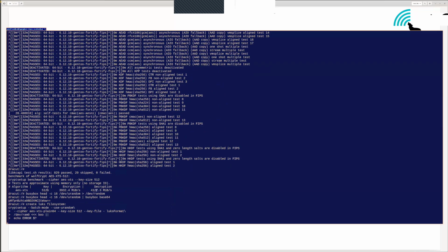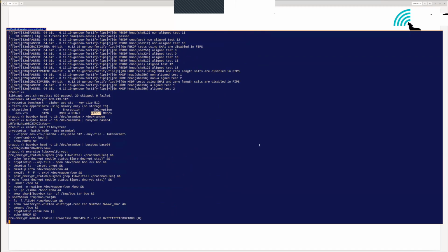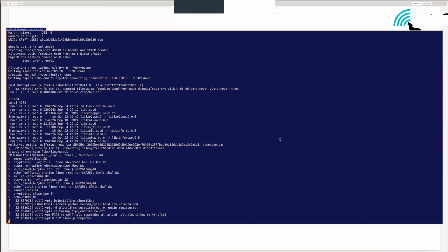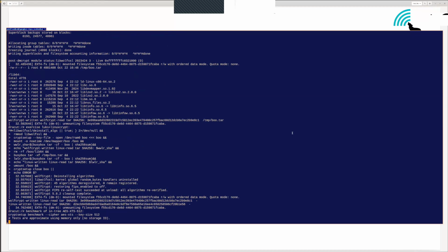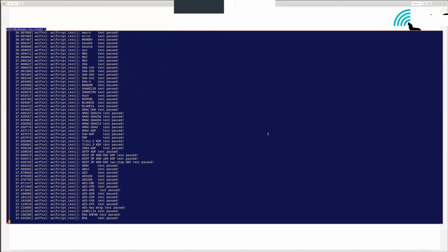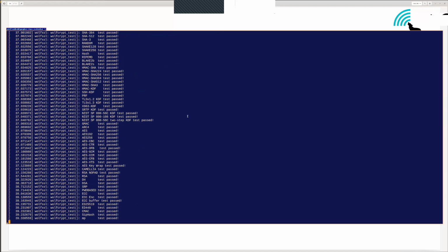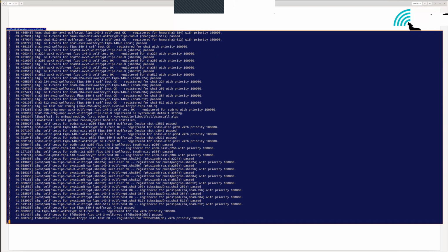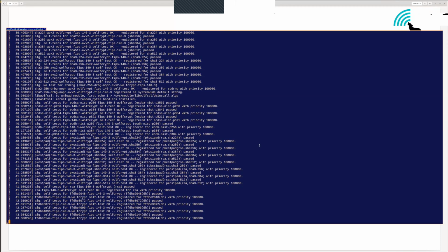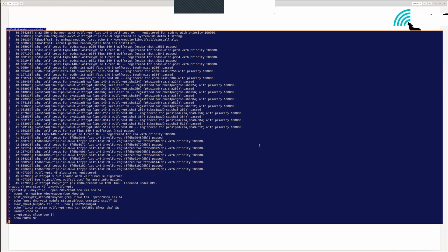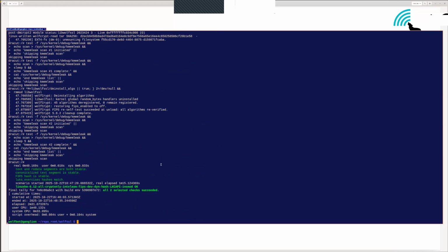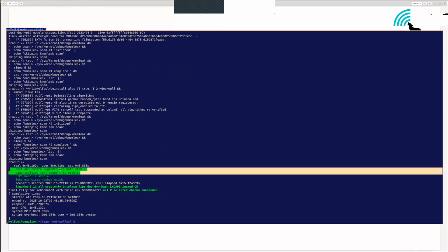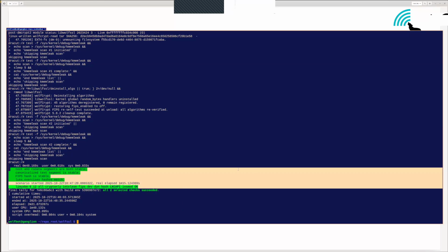So you see we're clocking about 4 gigabytes a second on the AES-XTS benchmark. That's for a single core, and that's with a full-size key, that's an AES-512 XTS. And then we do it a second time, and a second time registering. Oh, so it's also testing deregistration and now re-registration, and all done. So that is the end of it. So it's time for questions.